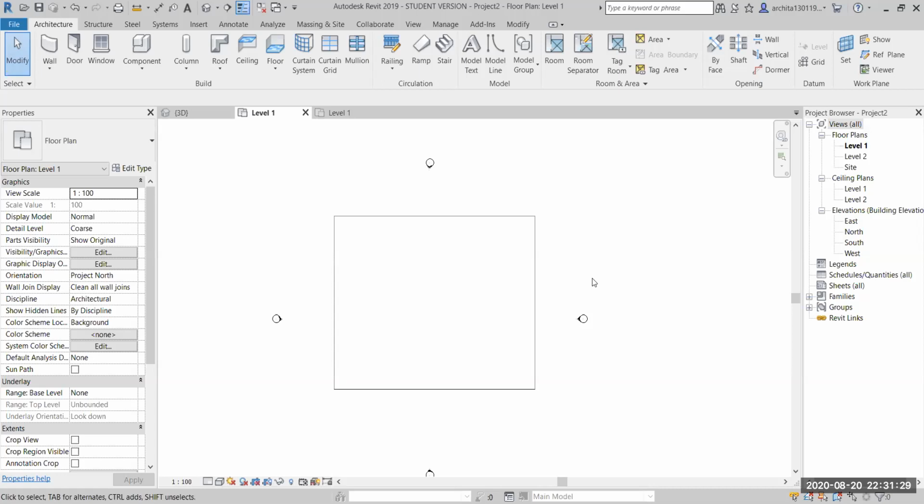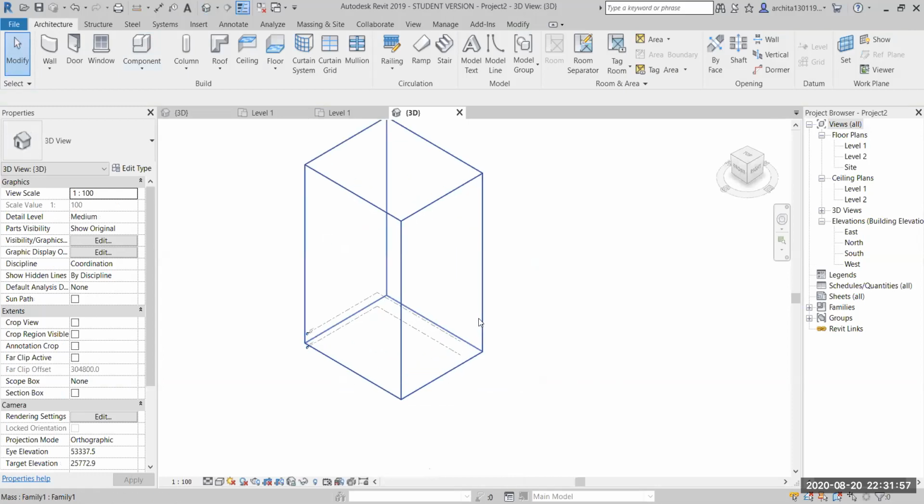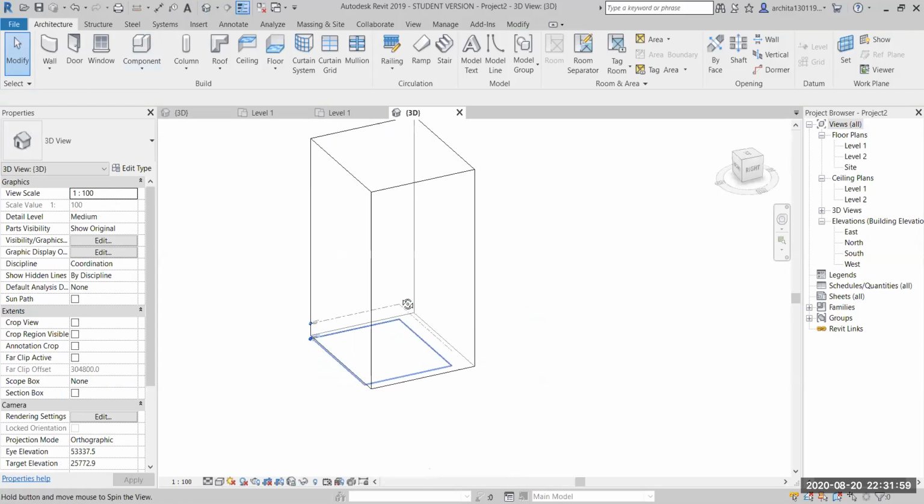Done, everybody? Can you see an option coming in front of you? Revit will turn on the mask, and a huge dialog box will appear. You just have to press OK and then place the mask. Now, in your 3D, it will look like this.